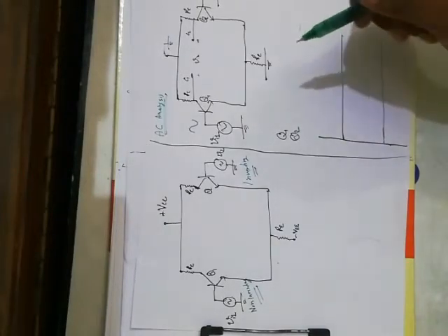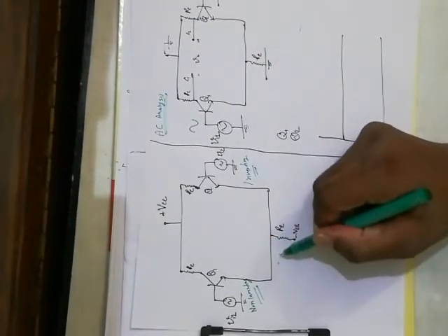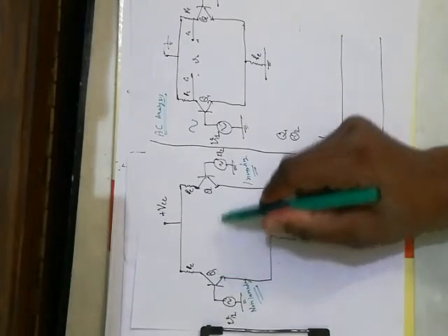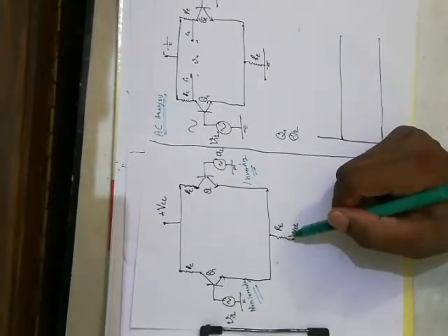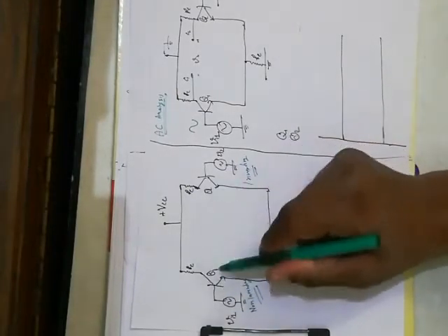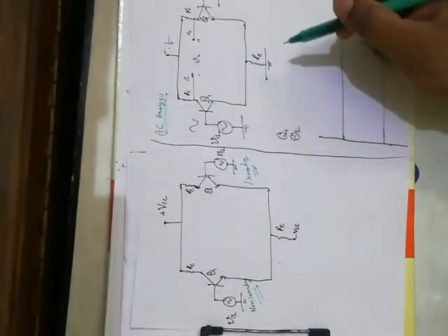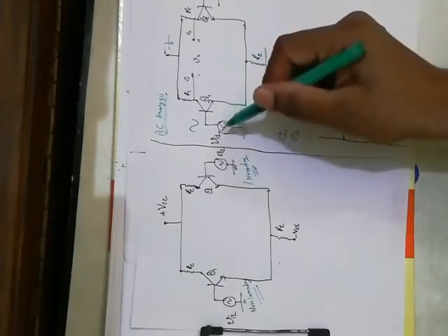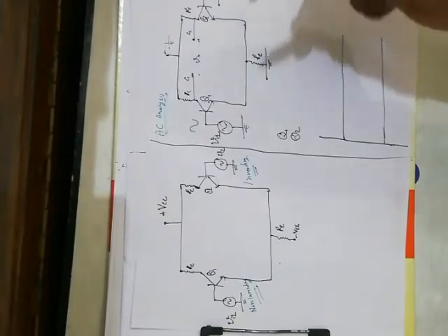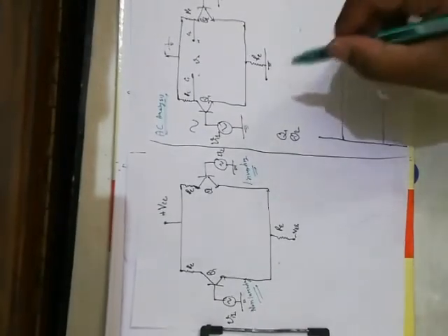That remark says that the emitters of both the amplifiers, this amplifier Q1 and Q2, are connected. That is why the effect of one signal is on both the outputs. So we will see how the one signal will affect both the outputs here. Both the outputs will be affected by the one input. Here we are using superposition, so we will deal with the one source at a time. Okay, let us start the analysis.